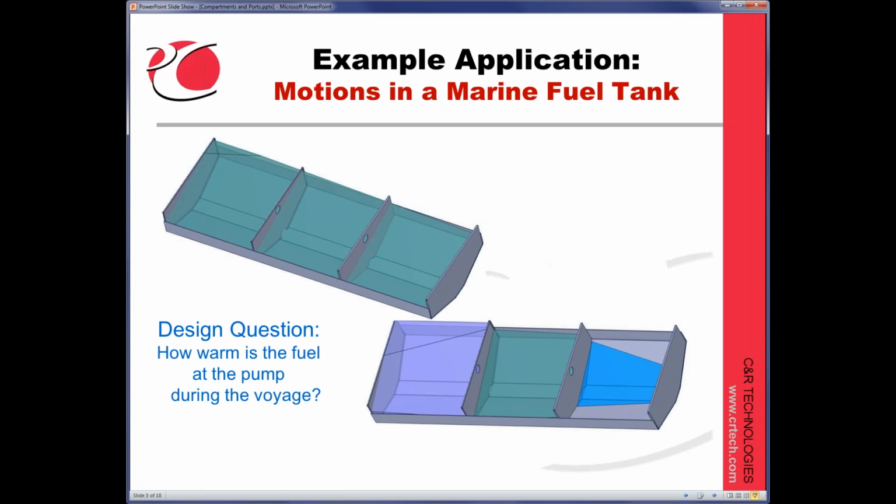So this isn't just a single steady state sort of analysis. This is a long-term transient with motions and so forth, a very complex situation, and you're asking to track the fuel temperature during the entire event. And that's something that is basically more than a traditional simple fluid network could handle, but it has to be less than a CFD code. Of course, a CFD code could handle that, but if we had launched it off a couple years ago, it still might be solving. It's a very complex problem for CFD.